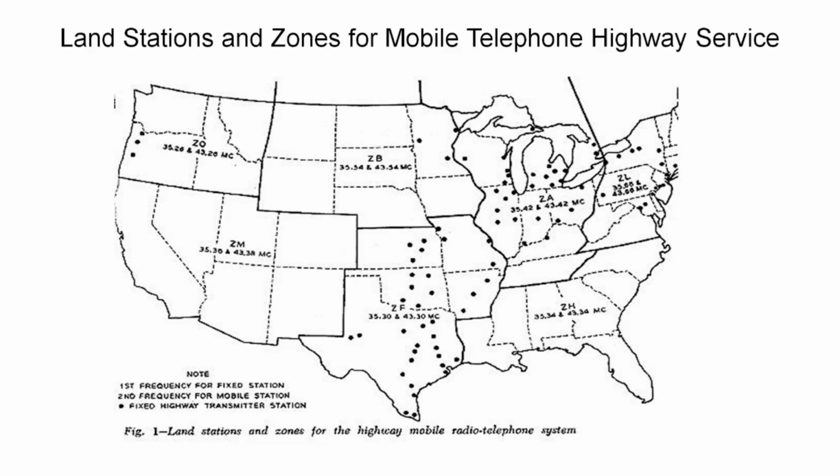And I kind of wondered about this when I first came across it. What are they doing for co-channel interference? But then I realized that they were worried more about E-skip interference. And with each zone on a different channel, even if there was E-skip, you wouldn't notice it because you're not monitoring a Texas channel or whatever.